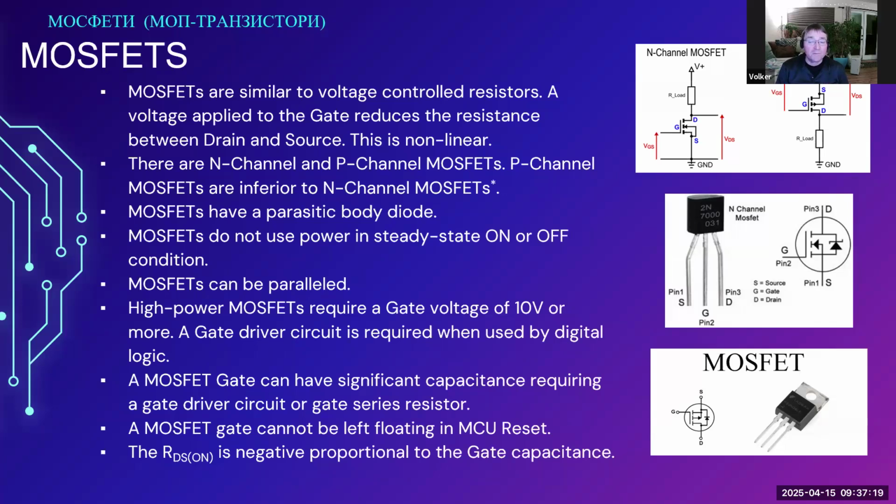So seeing a 150 amp rated MOSFET in that package is concerning because the package isn't really rated for that. You might be able to use it, but you would have to provide a lot of heat sinking on both sides of the connection.